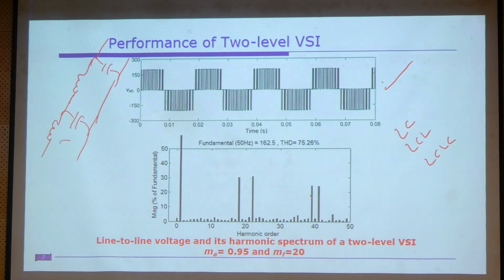By connecting an LCL filter and doing some harmonic analysis or resonance analysis, we can easily design a filter for this. But the drawback is that as and when you add a filter, it adds weight, and it also impacts the reliability.